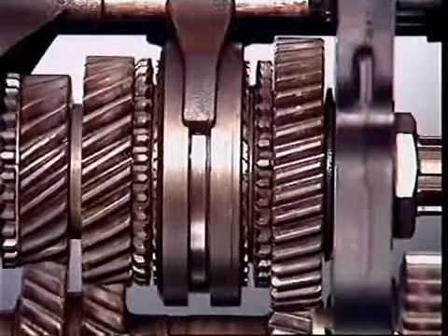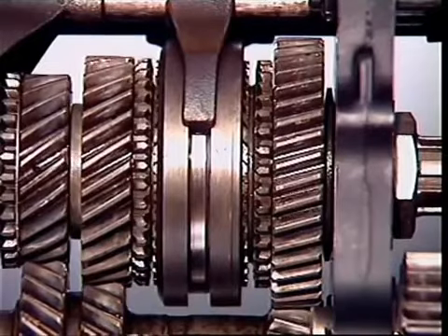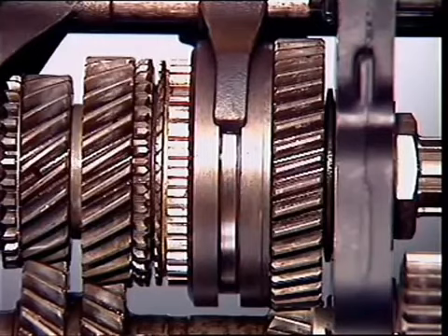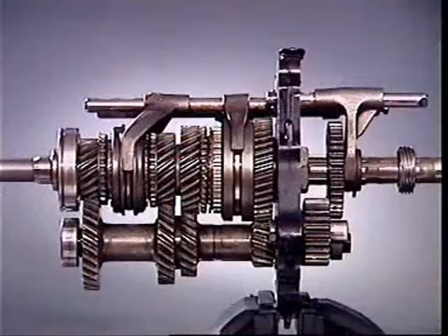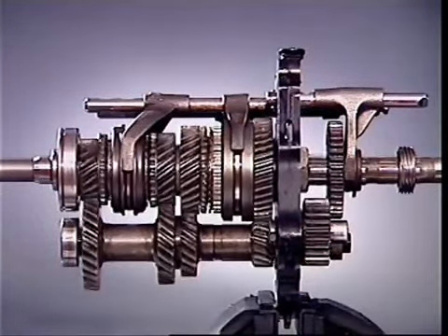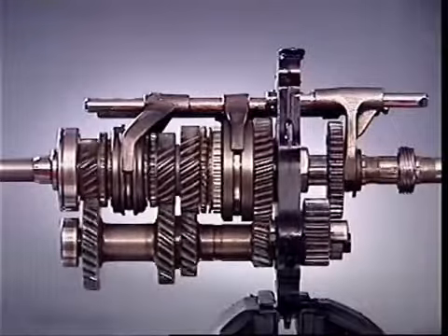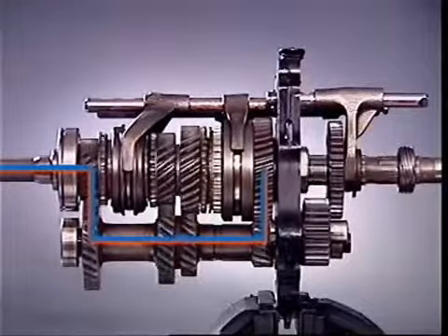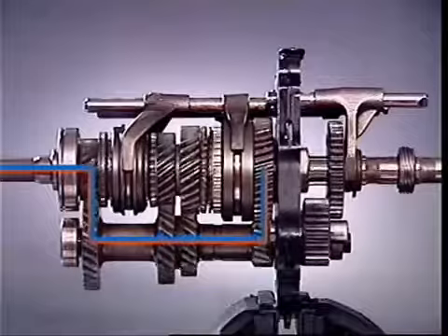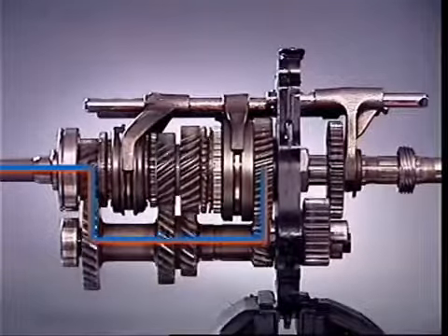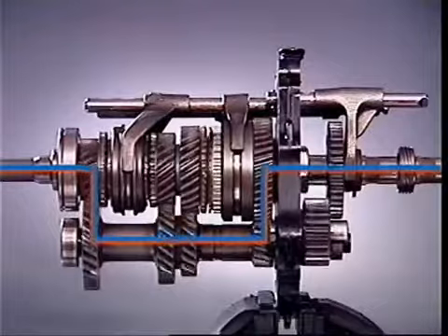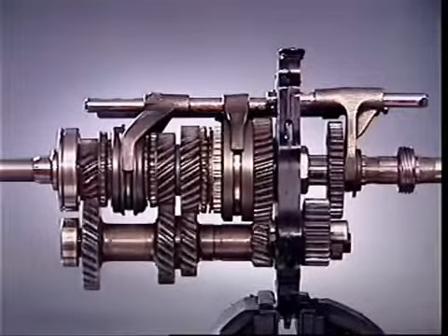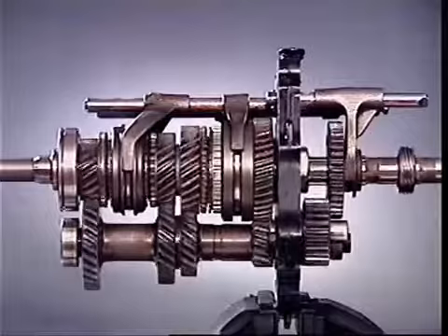Depressing the clutch pedal removes the engine load from the input. This allows an engagement sleeve to be moved into engagement with the external teeth on the gear selected. This locks the gear to the main shaft. When the clutch is released, the drive is transmitted to the input gears along the countershaft to the gear selected. Since this gear is now locked to the main shaft, it rotates and transfers the drive to the final drive unit. The speed ratio and the torque transferred depend on which gear is selected.